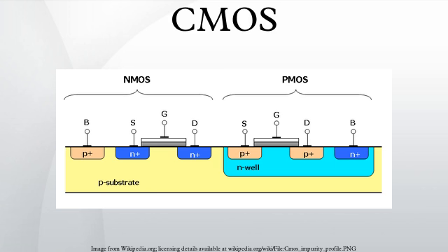Contention current in ratioed circuits. Dynamic dissipation, charging and discharging of load capacitances: CMOS circuits dissipate power by charging the various load capacitances whenever they are switched. In one complete cycle of CMOS logic, current flows from VDD to the load capacitance to charge it and then flows from the charged load capacitance to ground during discharge. Therefore, in one complete charge-discharge cycle, a total of Q equals CL VDD is transferred from VDD to ground. Multiply by the switching frequency on the load capacitances to get the current used, and multiply by voltage again to get the characteristic switching power dissipated by a CMOS device.